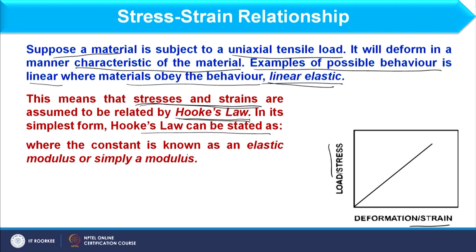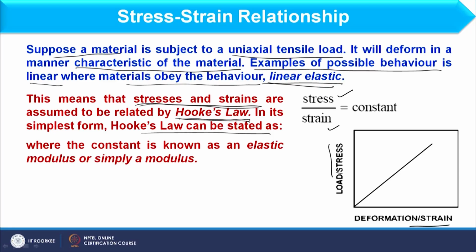So, till the material follows linearity, stress and strain can be represented by a particular constant. According to Hooke's law, stress divided by strain should be equal to a constant because linearity occurs. And that constant we basically call the modulus of elasticity, or simply the modulus.